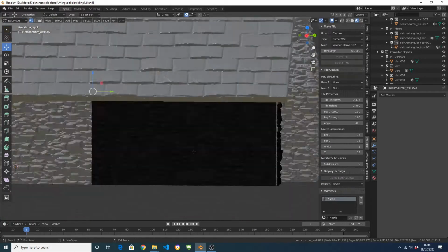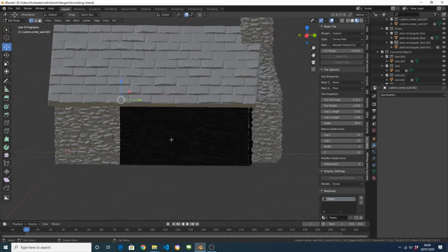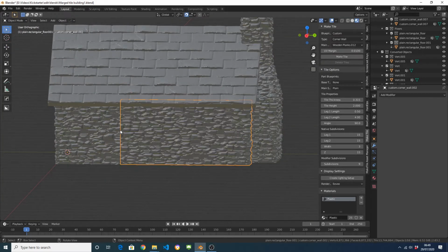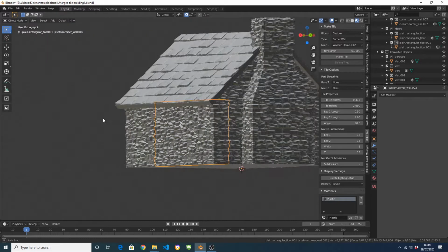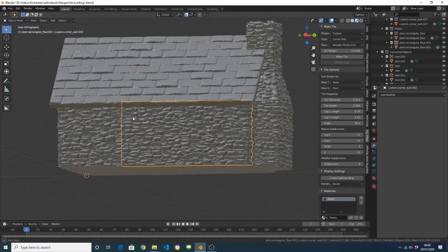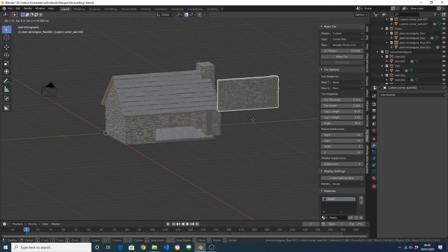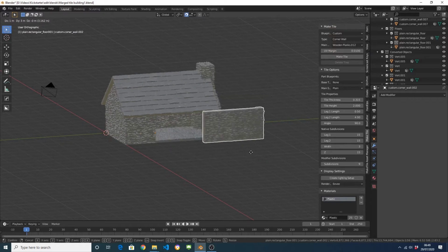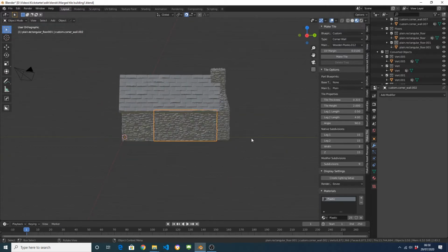Each of these is an individual vertex, and if we were to put this in our slicer, everything would be very slow. And these are still individual tiles. So we want to get rid of some of that geometry while keeping as much of the detail as possible, and we want to merge everything together.